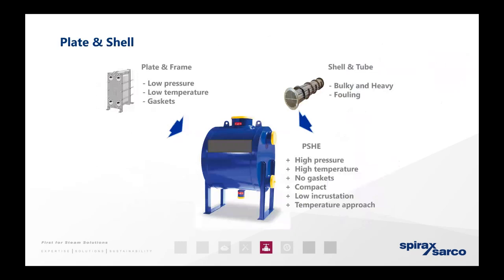As we show here, we've got the plate and shell. You've got the plate and frame in the top left-hand corner, and in the right-hand corner, the shell and tube. It's a mixture of both, which makes the plate and shell. They're designed for high pressure, high temperature, no gaskets again, so chemical compatibility is not an issue. They're compact, relatively small for what they're designed for. Low incrustations, so effectively there's not much build-up of scale. And temperature approach: it's quite easy to get these to reach temperature at a steady rate.